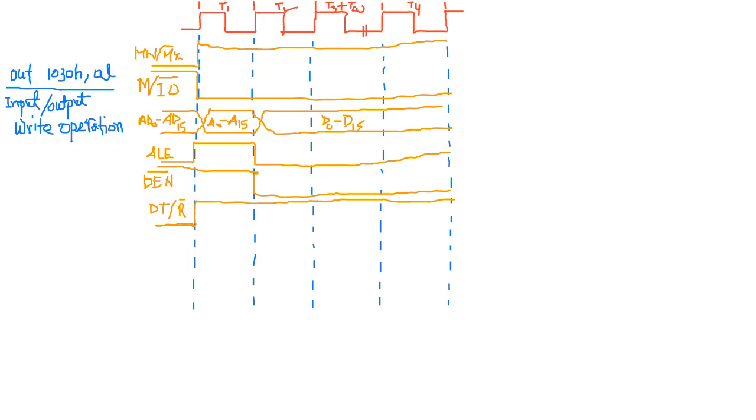Okay, so now what else, is it a read operation or write operation? So definitely it is a write operation. We need the write signal, WR, and it is also with a bar, and definitely during the data time it must be low. Must be low. Yeah, write signal.